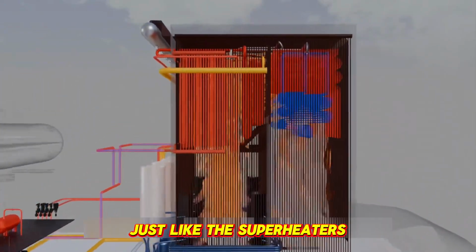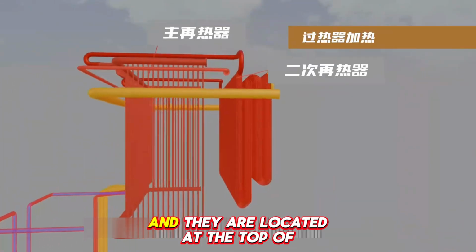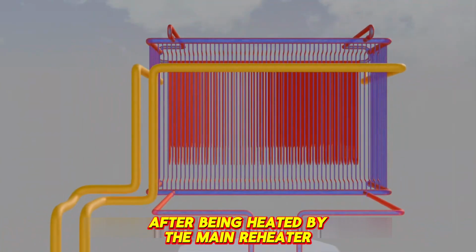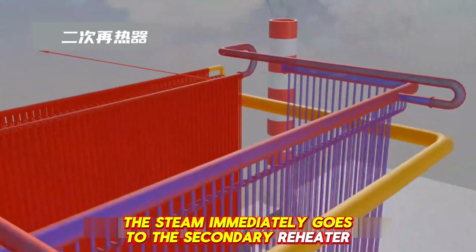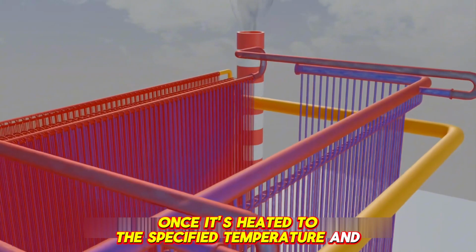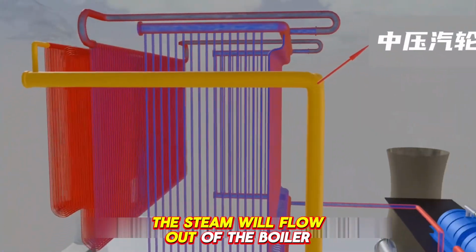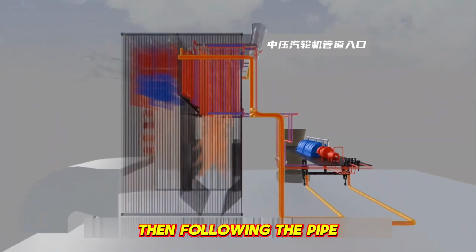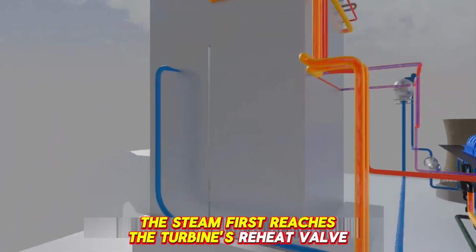Just like the superheaters, there are multiple reheaters, and they are located at the top of the boiler. After being heated by the main reheater, the steam immediately goes to the secondary reheater for further heating. Once it's heated to the specified temperature and pressure, the steam will flow out of the boiler through this yellow pipe. Then, following the pipe, the steam first reaches the turbine's reheat valve.